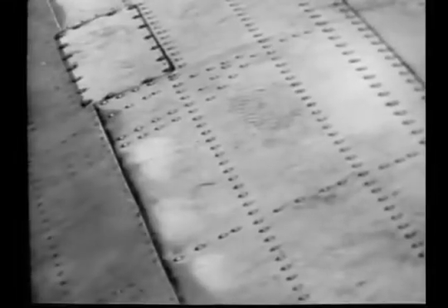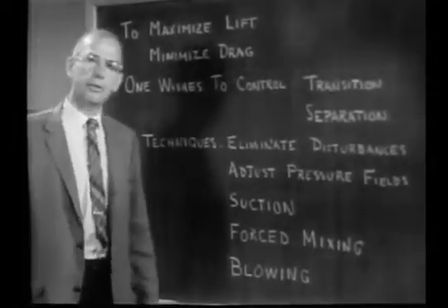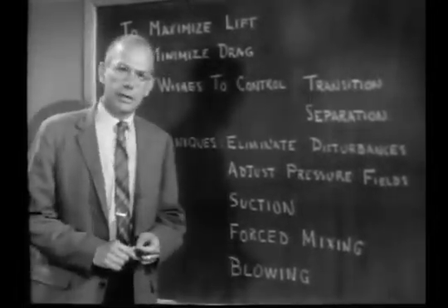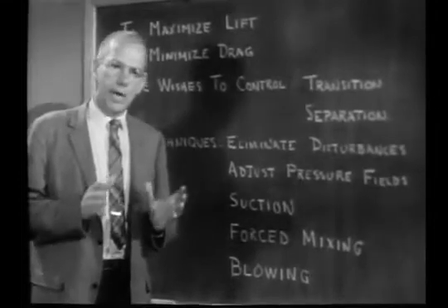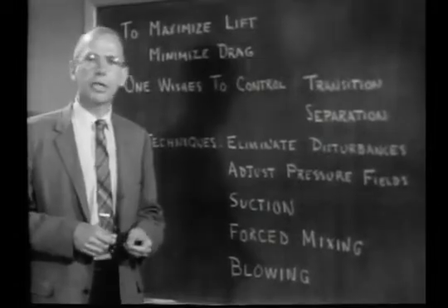The designer has learned to control some of these factors. Disturbances arising from rough surfaces can be reduced. Other disturbances, such as noise, vibration, or airstream turbulence, can sometimes be avoided or isolated. Designers have also learned to use the strong influence of the pressure gradient on the stability of the laminar boundary layer, that is, its ability to damp out disturbances. This can best be demonstrated by use of a pressure distribution tunnel.